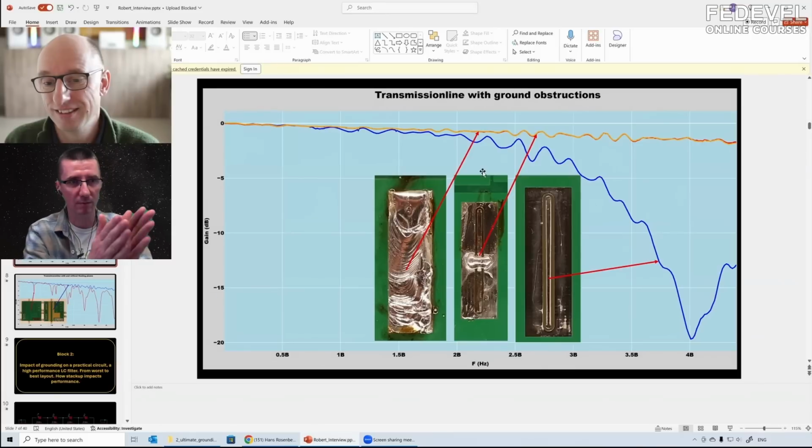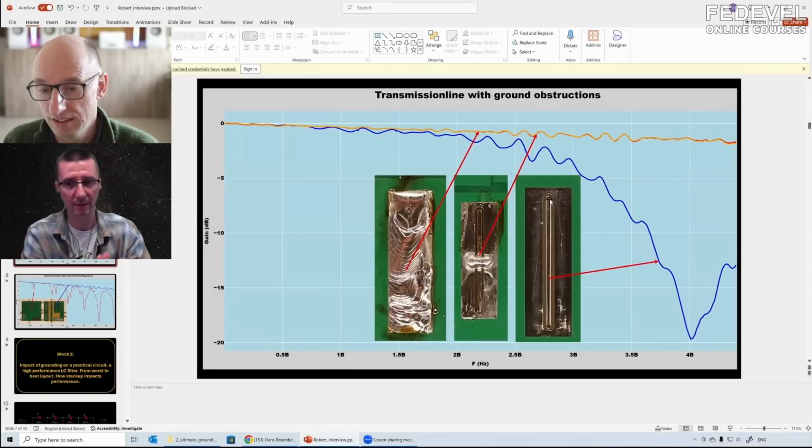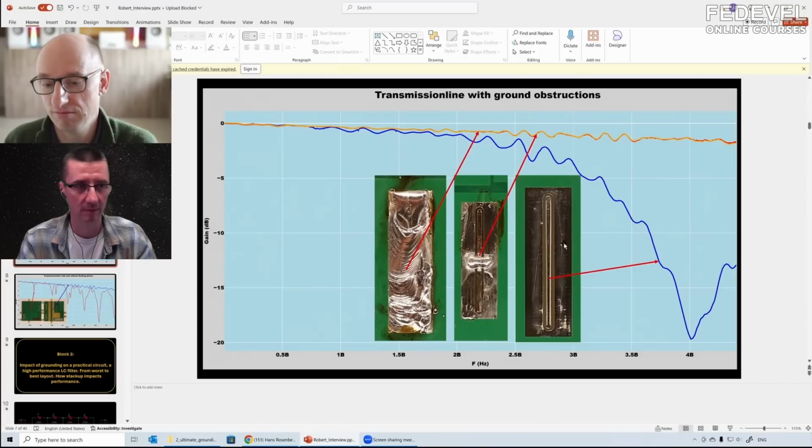And everything you did, you basically broke the ground plane which is under the track. Yeah, you can see it here. I put a trace in. I put a line in which was not part of the net list. So the PCB package made a cutout around it, and I removed the varnish, or what's it called, the mask. So I could cover it with solder if I wanted to do that. And then I was really surprised when I made this tiny little blob here under the trace that it exactly did the same thing as a full plane, really proving that return currents stay directly under their trace.